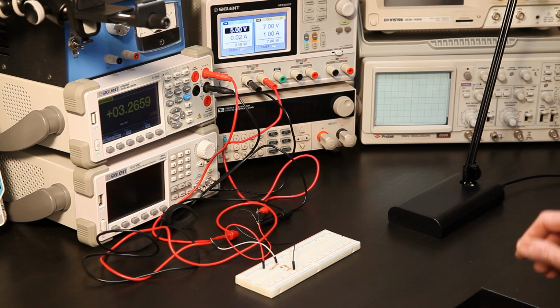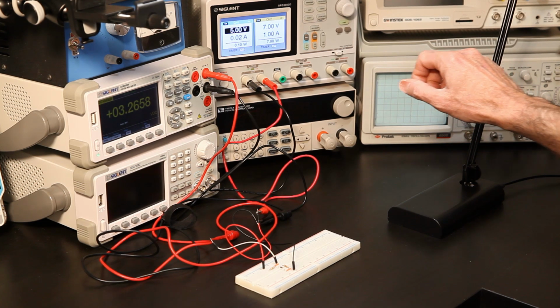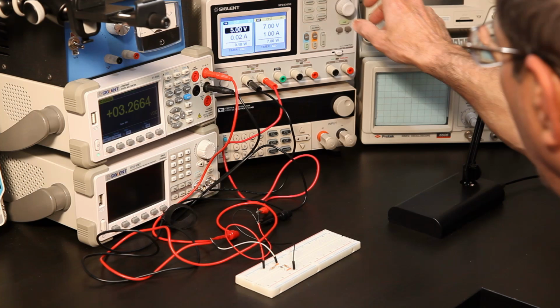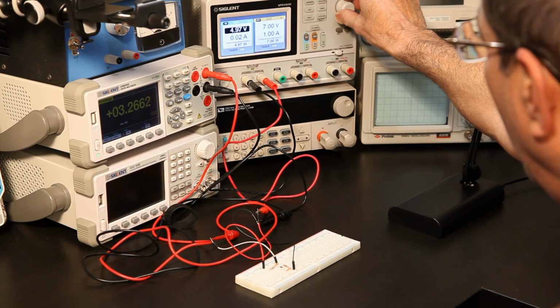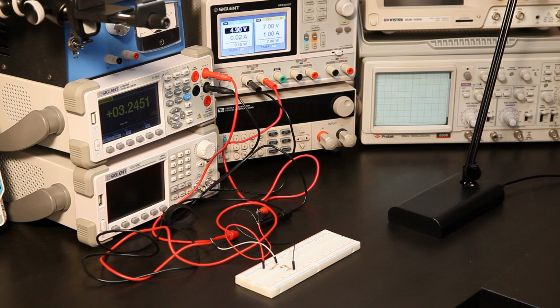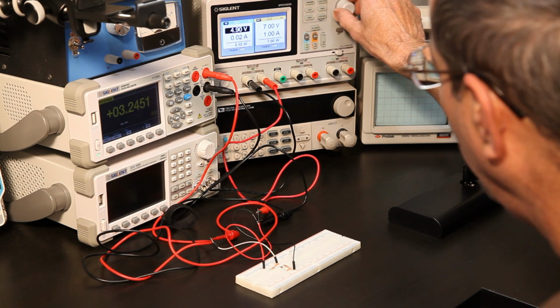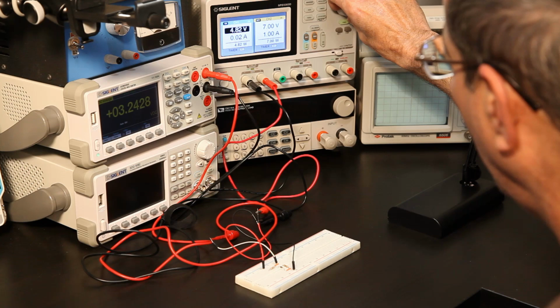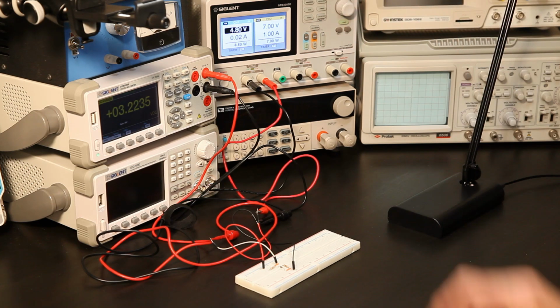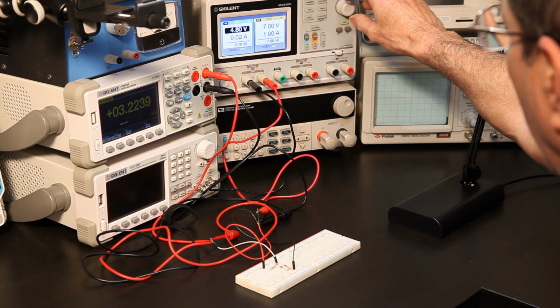And you can see at 5 volts in, it's holding at about 3.26, 3.27 volts. And let's see what happens if we have a 0.1 volt dropout. You see it's gone to about 3.24, 3.25 volts. And if it drops out some more, down to 4.8 volts, it's at 3.22. So not too bad. What we're seeing is in the tens of millivolts in terms of change.